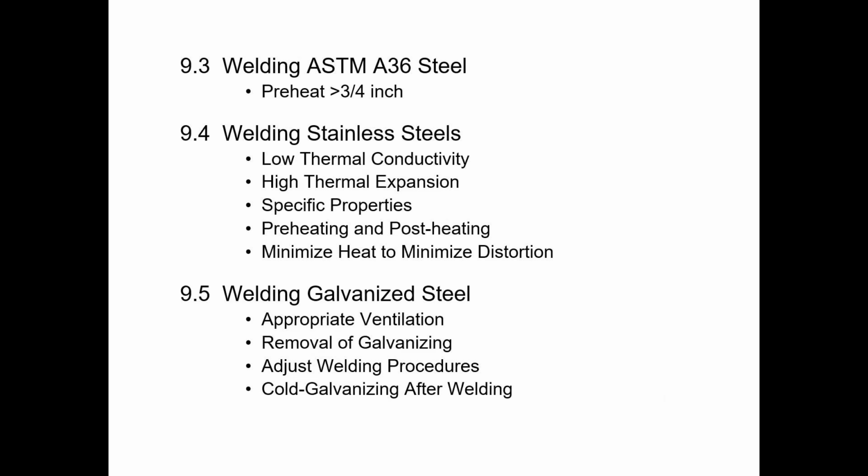You can weld galvanized steel as well, but in case you were not aware, galvanizing is actually a chemical process that the steel material is put through that applies that coating. So whether it's hot dipped or sprayed on galvanizing, when you weld it, you are vaporizing that chemical coating that's on the surface of that steel. That vaporized coating can be noxious. It can be poisonous. So make sure you have appropriate ventilation and you're wearing an approved mask to keep you from breathing that in.